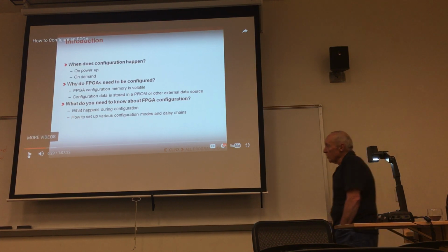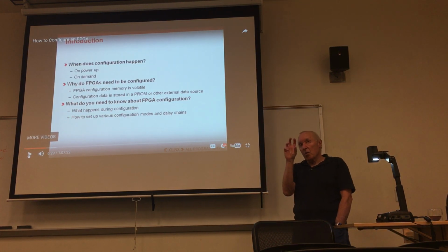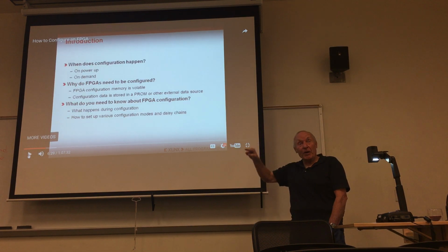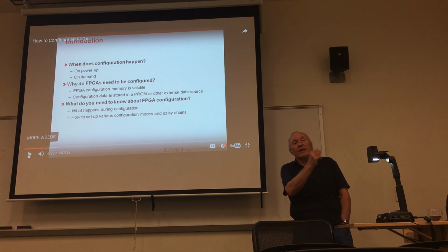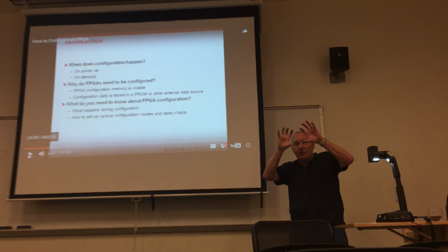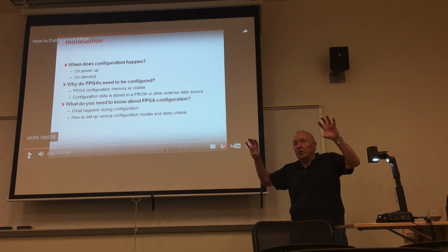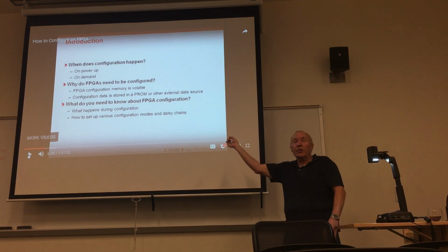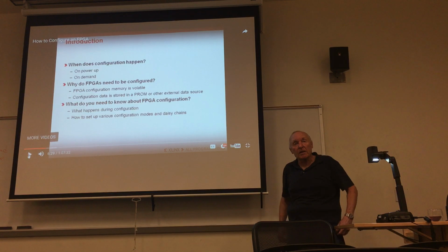Let me explain that term daisy chain. I've got on the board a non-volatile memory that's got configuration information. I'd have configuration information for 3 or 4 FPGAs that are on the board, all contained in that one memory. What you have to do is effectively create a shift register so that you shift the data in through all of the FPGAs. They're kind of daisy chained together to form a big shift register where instead of flip-flops, you've got FPGAs. And the one memory chip serially configures all of the chips simultaneously. That would be a daisy chain.